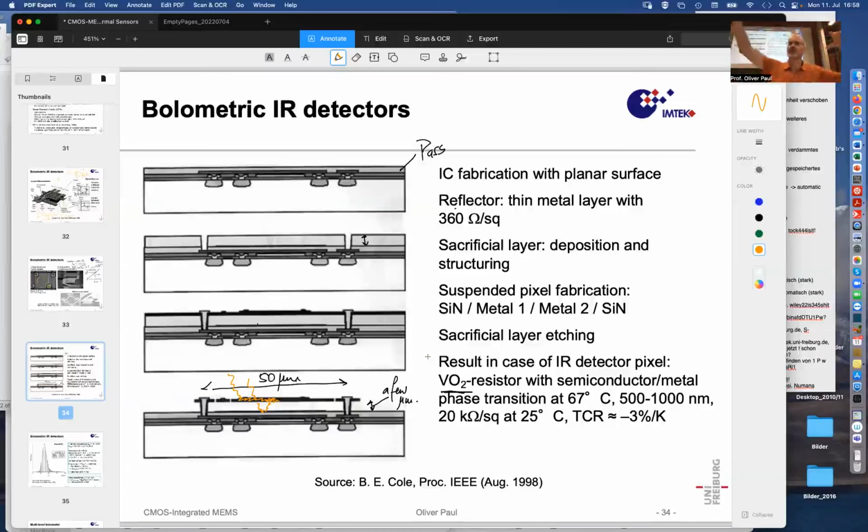Solar cells have the sunlight that comes in and crosses the sensitive material, the PN junction, and then it's at the back. And if it went out, we wouldn't have the efficiency that we now have, so 20% or more. The back is also metallized so that the light can move back through the silicon a second time.